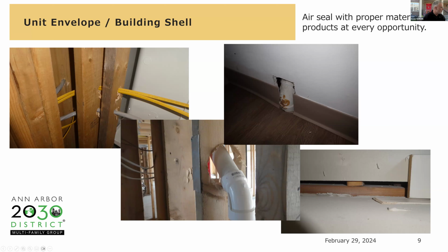You need to use the right materials. Here, for the picture in the upper left, we can use caulk and just caulk these holes up. For this one, I would probably try to use something to close off this hole, like a piece of cardboard or plywood, and then seal that to the 2x4 itself.